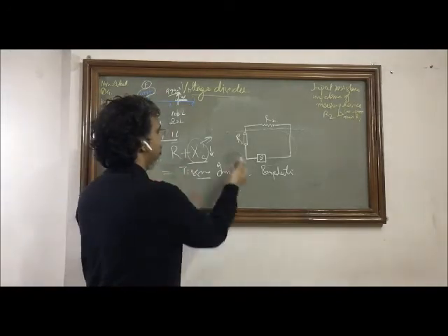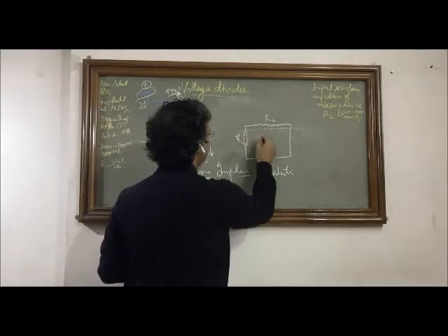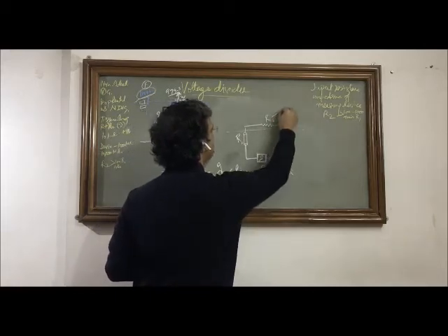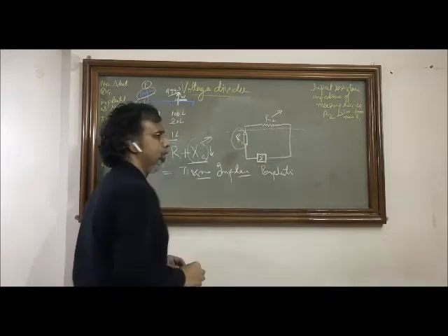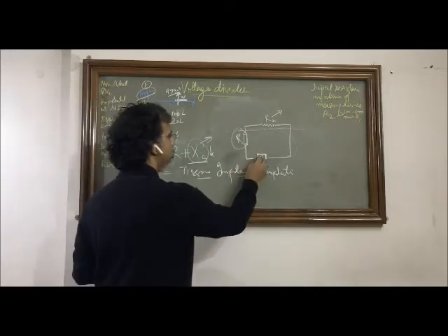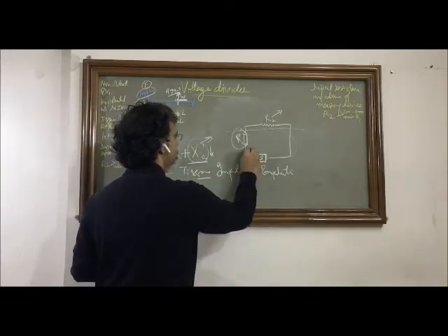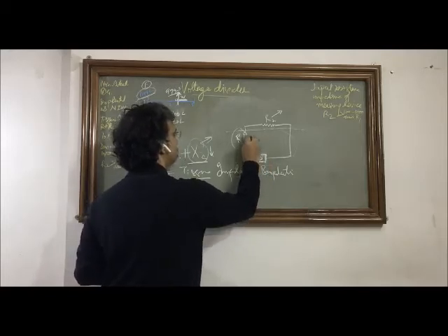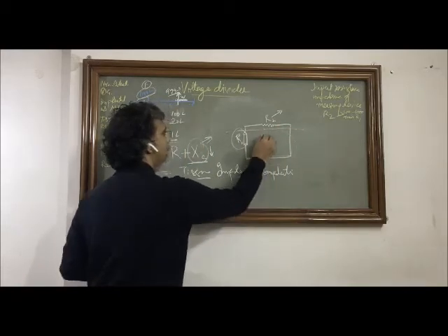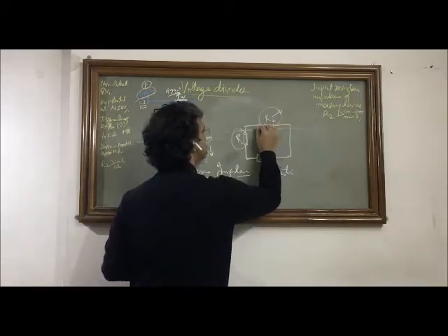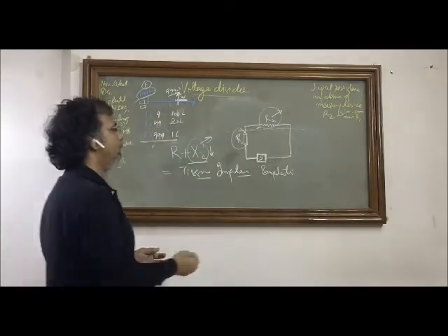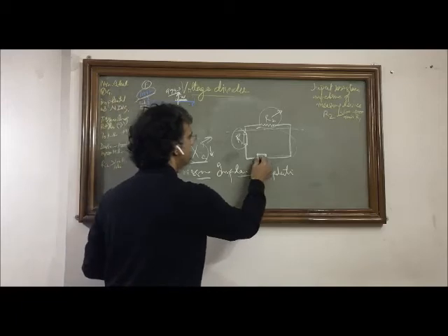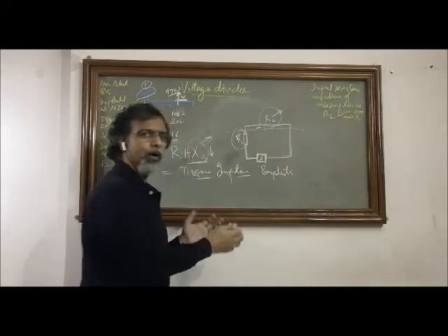Now applying the same analogy, if we want to measure this potential difference, make this value very large compared to R1, because the energy the charges take from this potential will be consumed in this complete circuit, and the higher the value of R2, the more energy is consumed across R2 only, and a very small portion of the energy will be consumed in the rest of the circuit, that we have already understood.